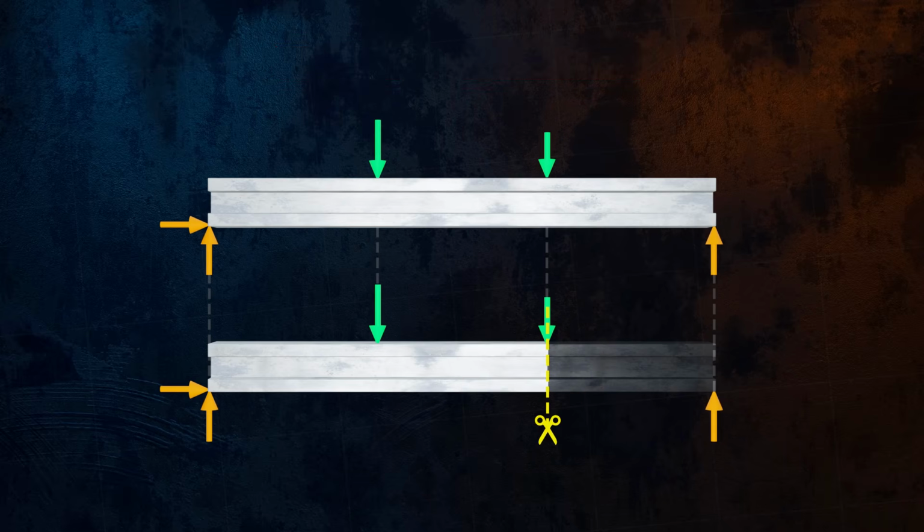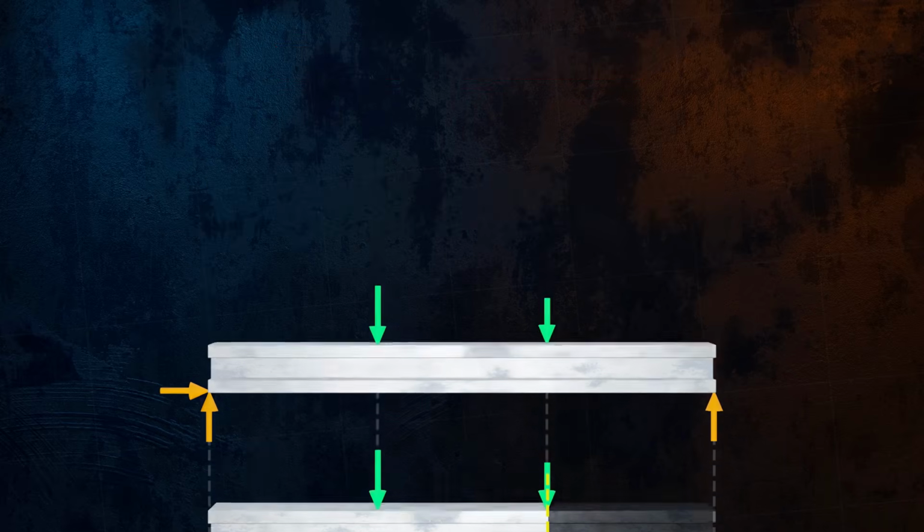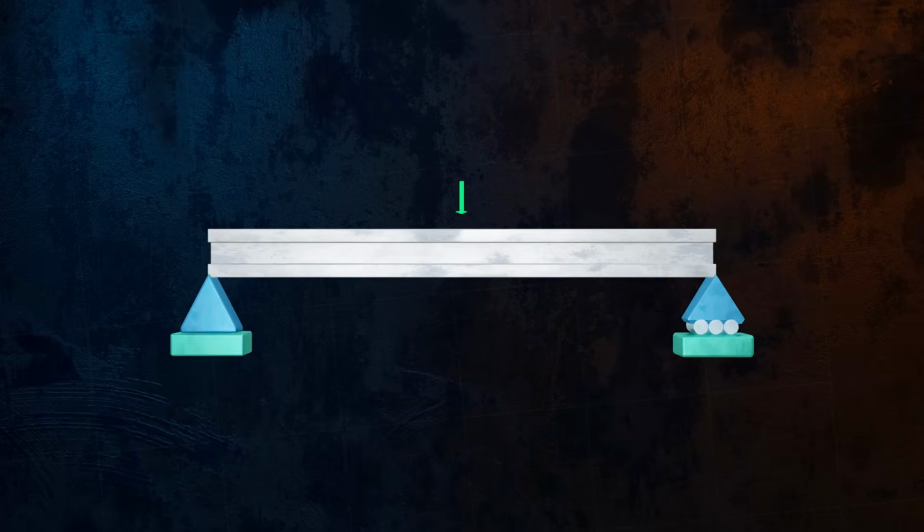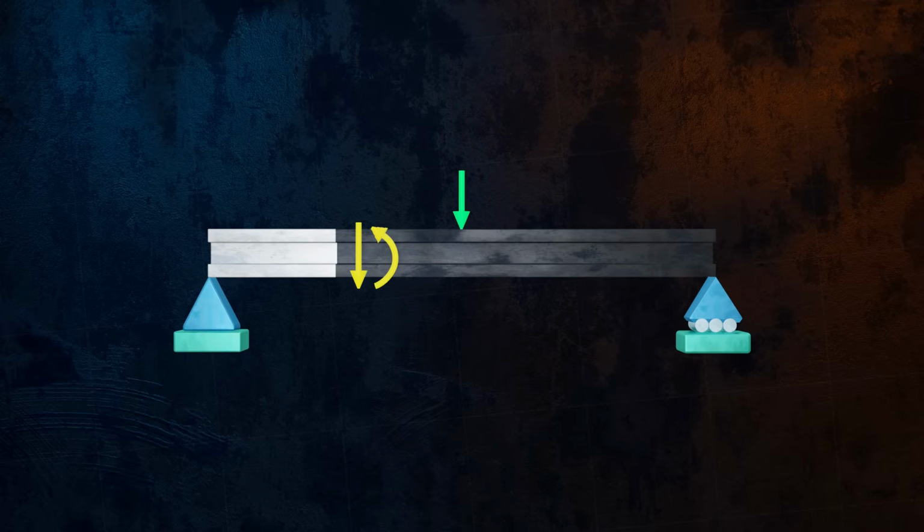Now is a good time to define the sign convention we will be using. Applied forces will be positive if they are acting in the downwards direction. For shear forces and bending moments, the positive sign convention will be as shown here.